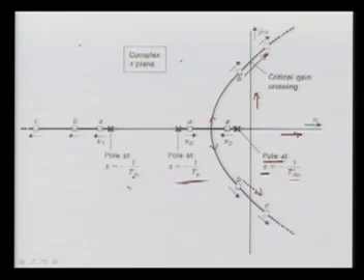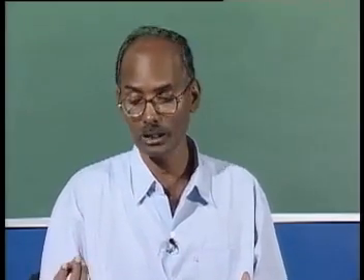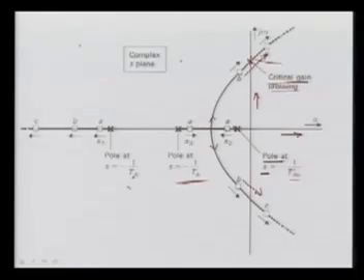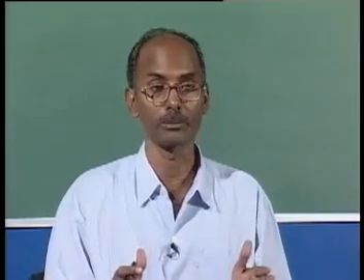So we find that the crossing here is called the critical gain crossing, and the root here gives the oscillation. The system will start oscillating even though it has not crossed at this point, and then a small perturbation or small disturbance may lead your system to be unstable. So we have to decide our gain up to this point, or below that, and then our system will be stable. This is without any compensation technique, without any way to improve the stability of this loop.